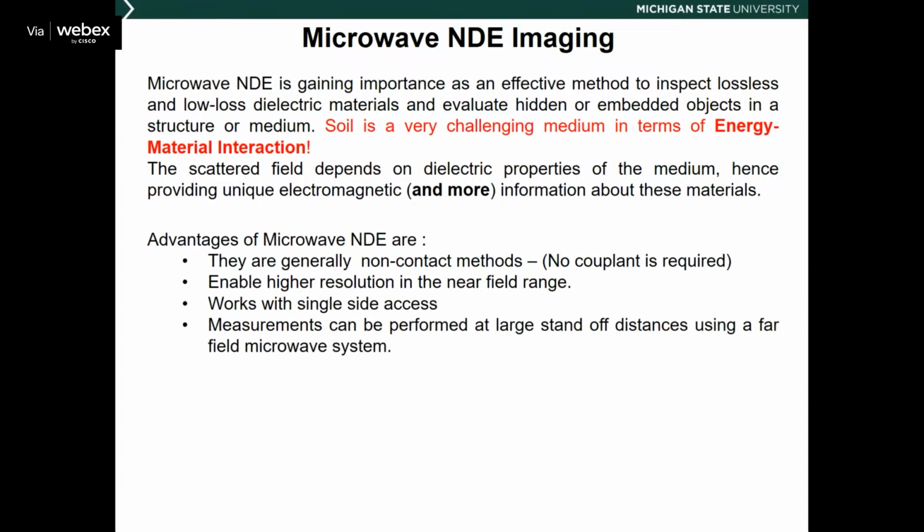The advantages of microwave NDE are not just limited to soil or root imaging here. They are usually non-contact methods. It enables high resolution in the near field. It can work with single-site access, and it can perform at large stand-off distance using the far-field microwave imaging system.